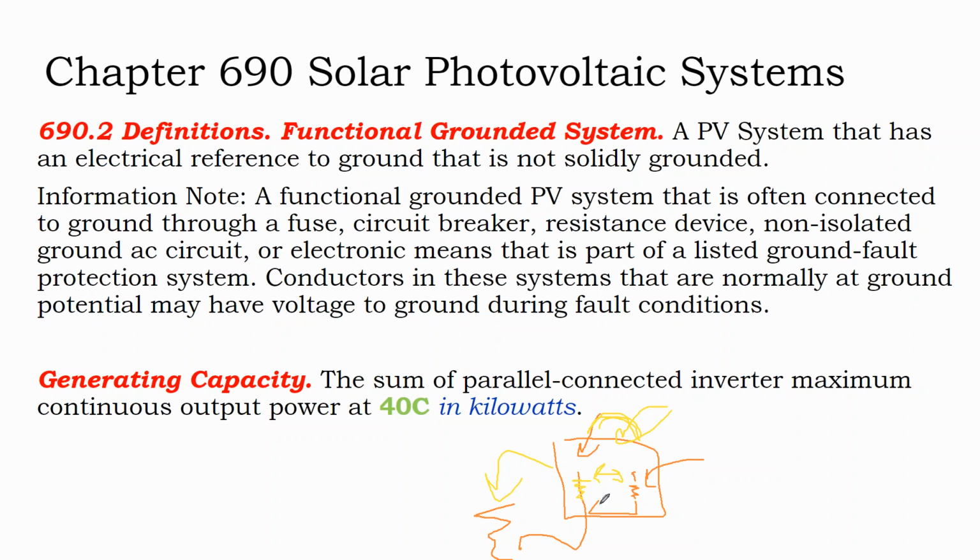The DC operating circuits are physically isolated from ground. And it requires an extra disconnect switch and an extra piece of overcurrent protection, so it is a little bit more costly than a negatively grounded system. And they had to figure out how to do ground fault detection for it. And so where this word mess comes from is that it used to be quite common to have a negatively grounded solar inverter.